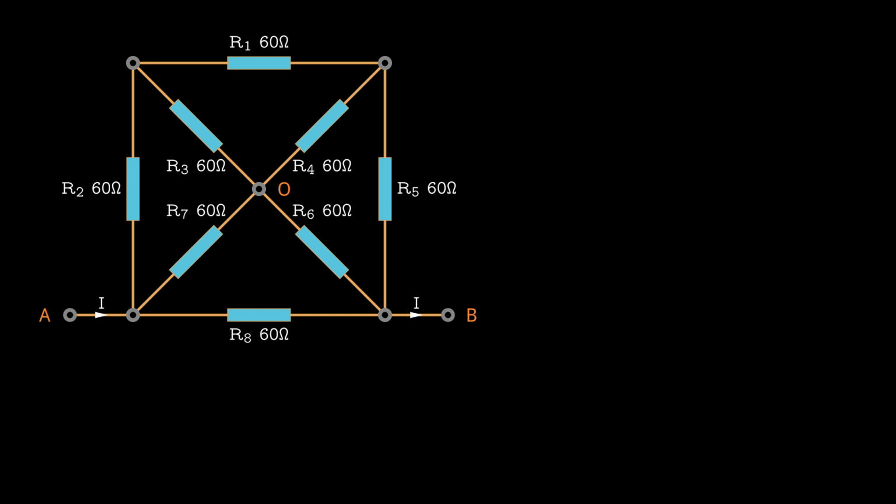This circuit clearly exhibits mirror symmetry, as it is symmetric along the line connecting points C and D. The line of symmetry passes through resistors R1 and R8. Unlike previous cases, we cannot remove these 2 resistors because the symmetry line does not align with their direction.